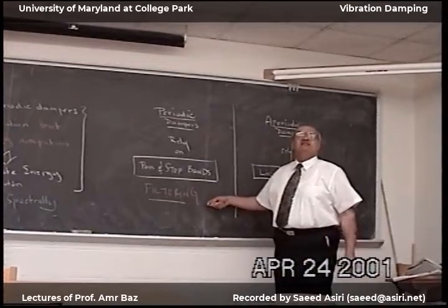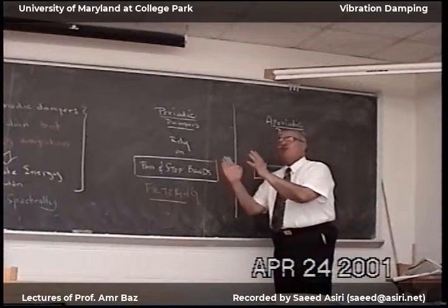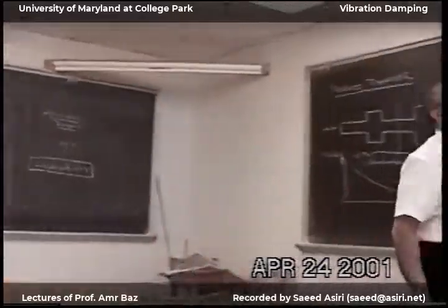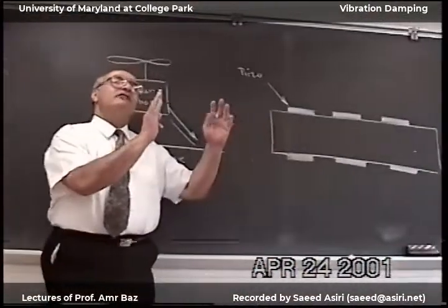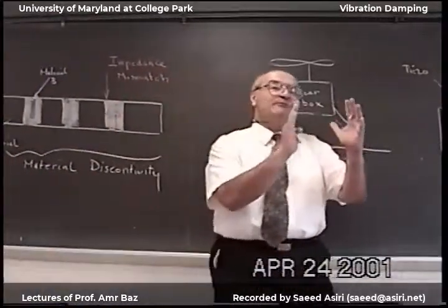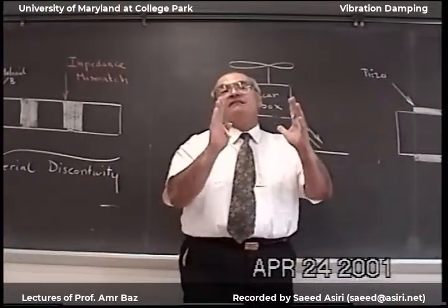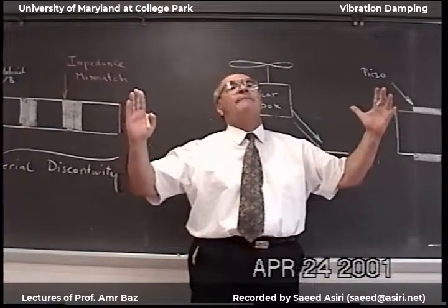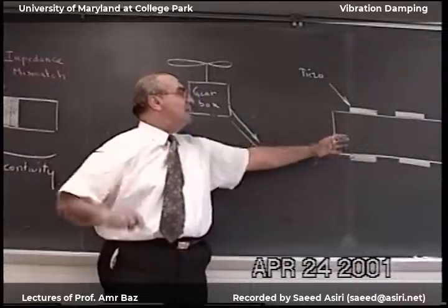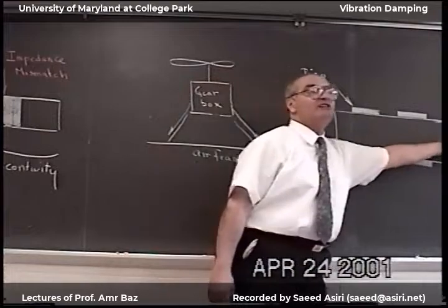So I can generate here, for example, low pass filter, high pass filter, notch filter, or when I do the periodicity, I can make the low pass move, the boundaries of the low pass, the boundary of the high pass move, the boundary of the notch filter move. I can tune how big is the low pass, how big is the high pass or the notch filter. So you can tune this very easily because you can program the control gain that is associated with any one of these.